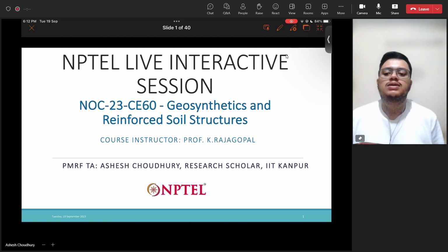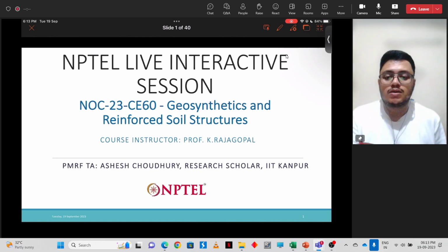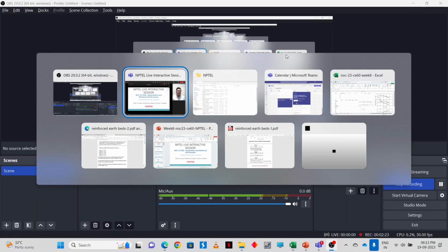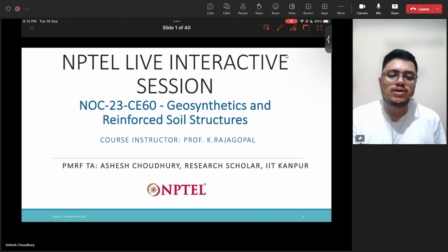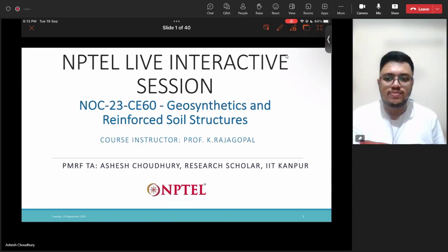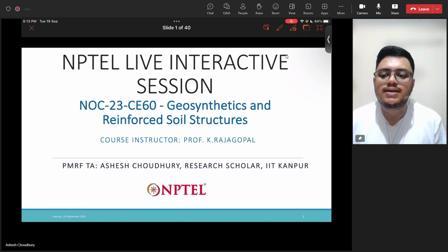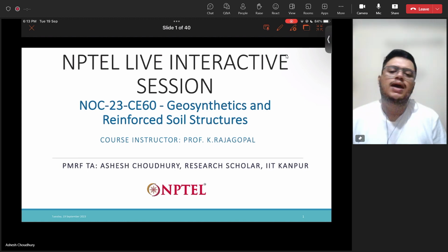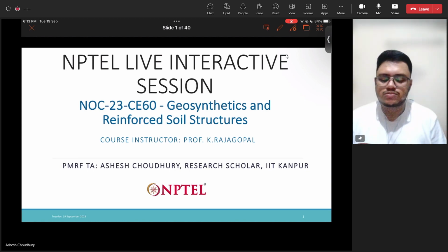There we saw that if we use a layer of geotextile or geogrid, we can reduce the thickness of the aggregate layer by a large extent, isn't it? Right.